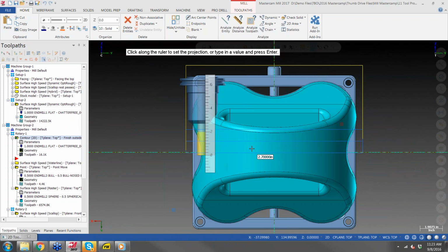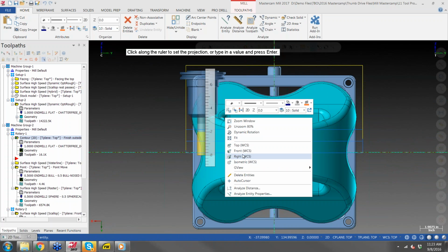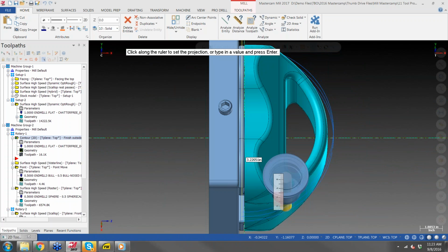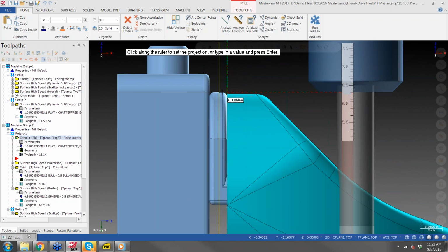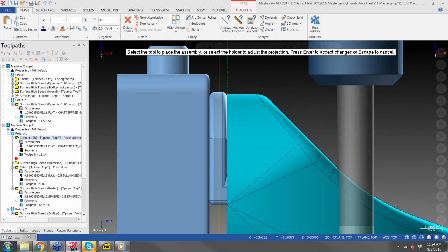Because right now it's basically a visual sort of tool. It's not necessarily something that's going to squawk at you when you're going to be hitting something. But what you can do here is see how it adds this additional red line as I drag away from the projection. So what I can do here is say, okay, 6.3 is about the top of my part here, and even 6.35, let's say, is the top of this outer extent of my work holding. So I can basically type in here and say, okay, 6.5, I know for sure will clear the part.